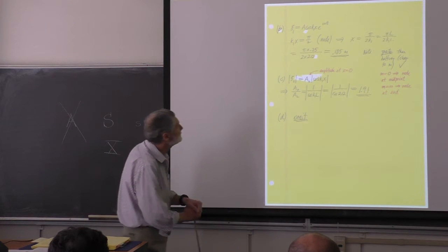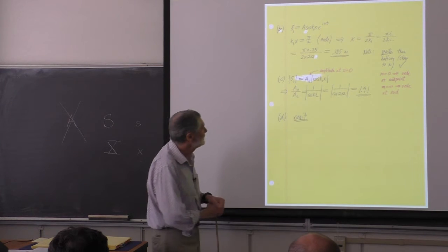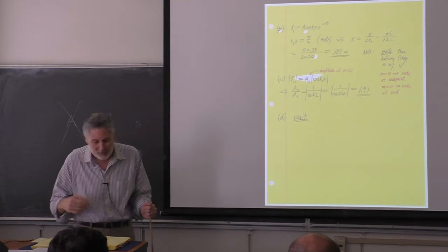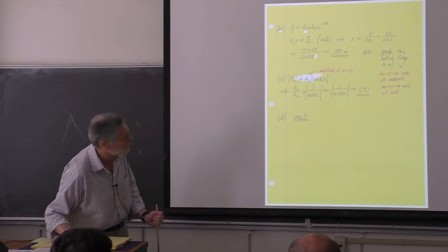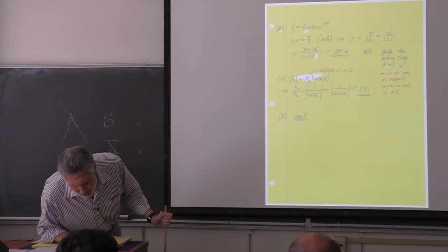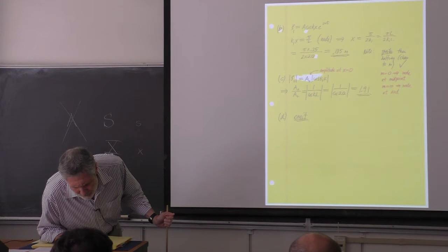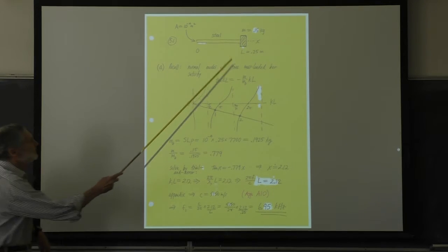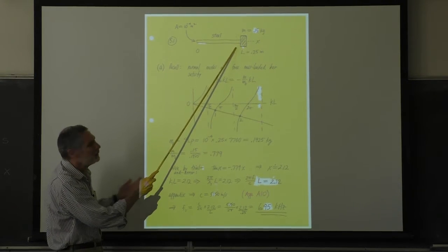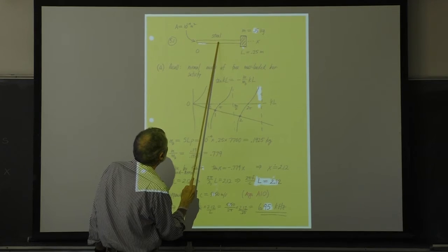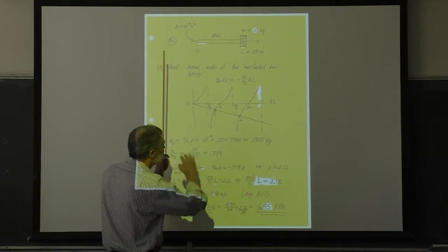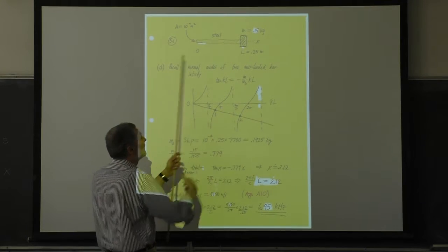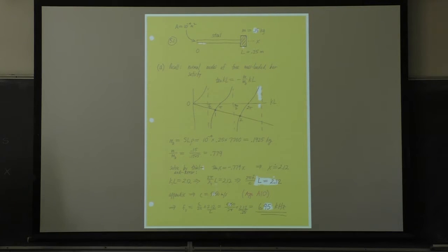Okay. Oh, finally, this is interesting. We're asked the ratio in part C here. In the fundamental mode, what is the ratio of the displacement amplitude of the free end to the mass loaded end? Well, we know this is going to be less. When you mass load this, the node moves over here, and so the waveform is going to look like this. It's going to have less amplitude, but precisely what is it?